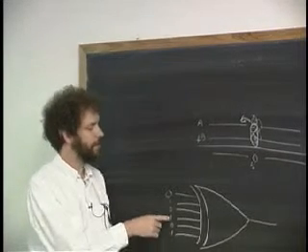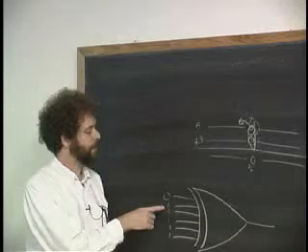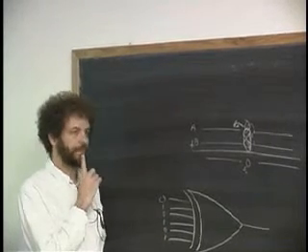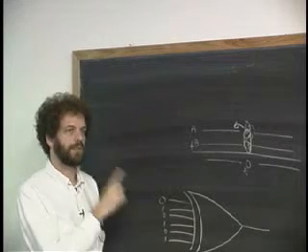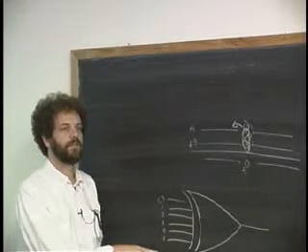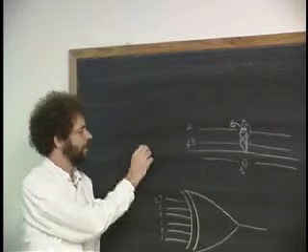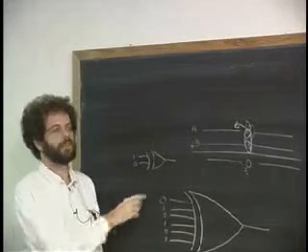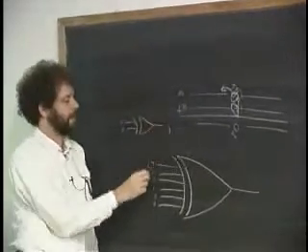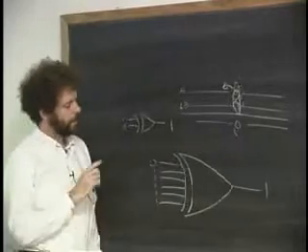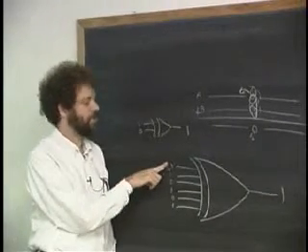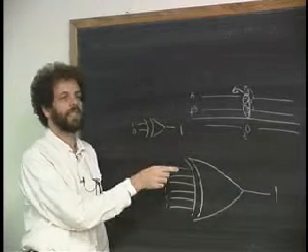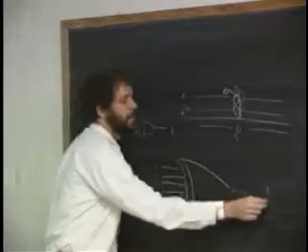It's counting how many ones there are, and it's seeing if the number of ones is odd or even. Now, is the number of ones here odd or even? Odd. So what is the XOR of all these things going to be? Well, you can think about it in the easy case where there's only 2 bits. Here's another one where it's odd. What's the XOR of 0 and 1? 1. So that's 1. But look at what takes place here. What happens if I change any of these bits? If I change this one from a 0 to a 1, what's the output going to do? Switches from 1 to 0.